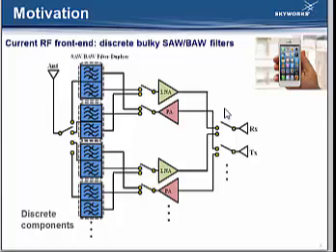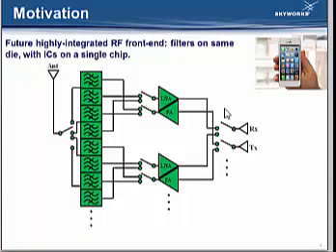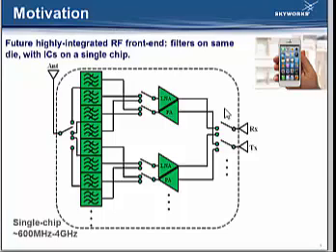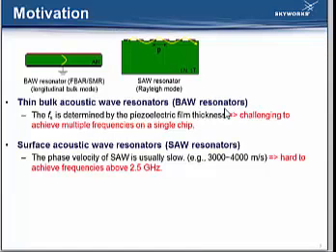the other RFIC components. In a trend toward high integration and co-design of the RF front-end architecture, high-performance and CMOS-compatible microacoustic resonators are highly desirable for the future single-chip RF transceiver. And the filters should preferably cover the frequency range of around 600 MHz to above 4 GHz. However, the current BAW and SAW filters have limitations to enable this integration.